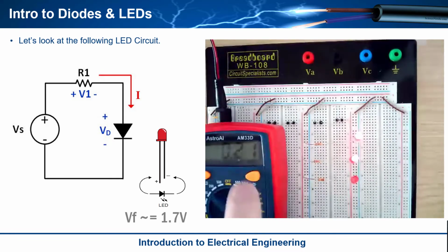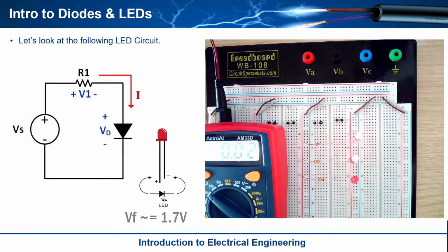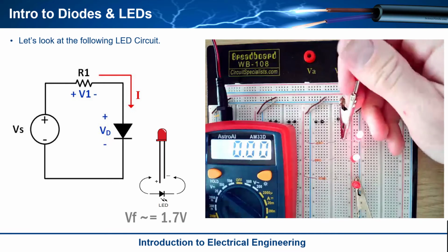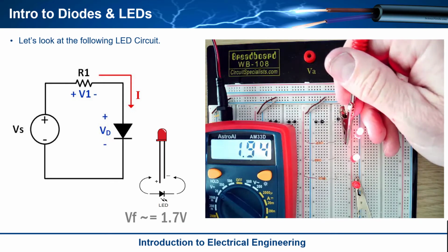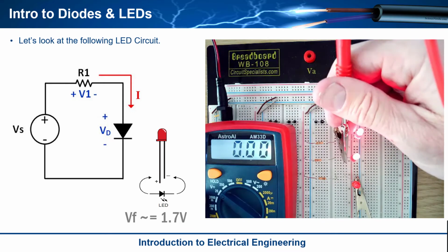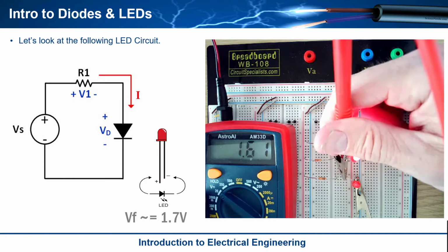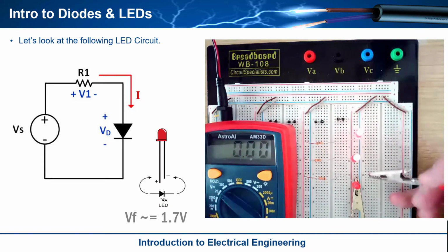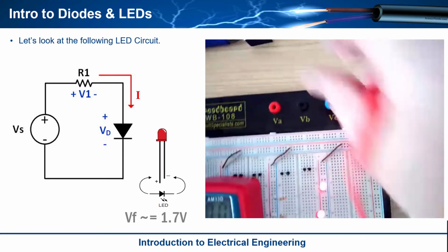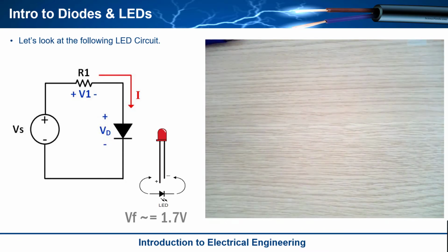So I'm going to come back to voltage, and let me clip onto the ground right here, and then measure the forward voltage of all these things. The first one was what we already did, which is 1.95. This is the 1K, 1.72, and then this is the 10K, 1.6. Our forward voltage is dropping when the current goes down. And that is nuts. That is crazy. Why would that forward voltage drop?